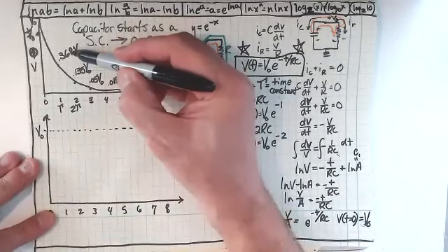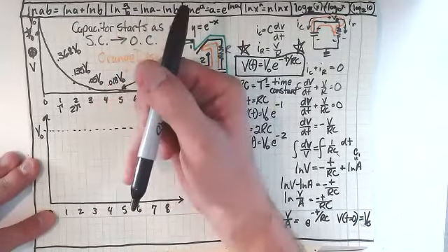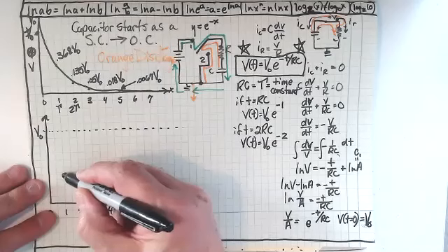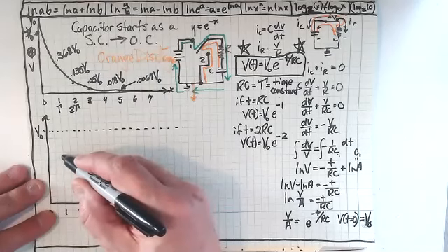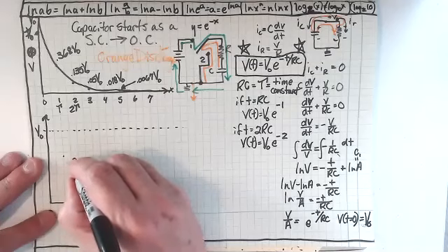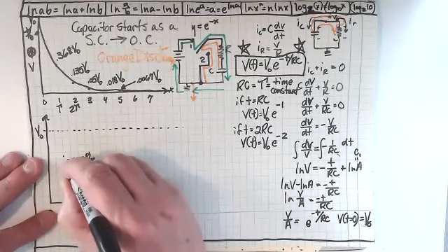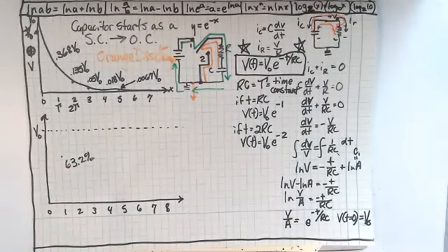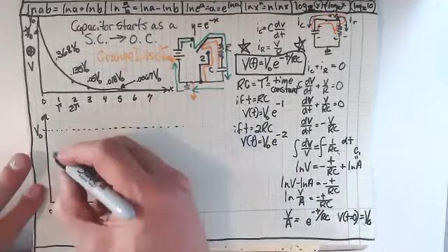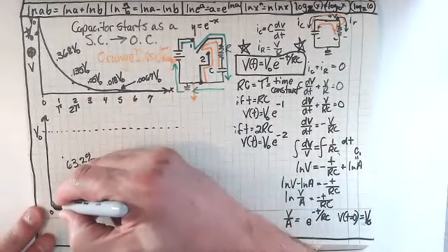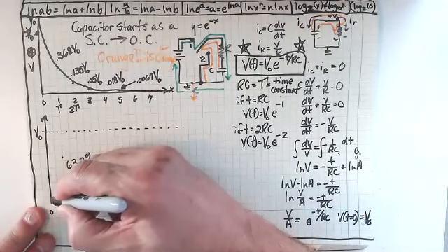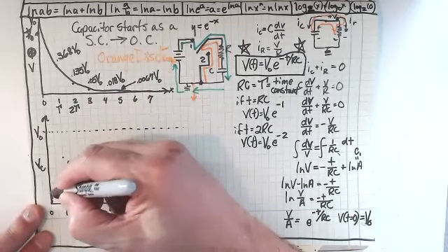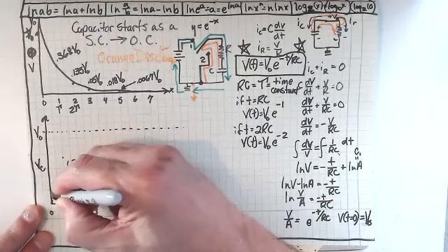So what I would do is take the 36.8% off 100%, and that would give me 63.2%. So 1, 2, 3, 4, 5, 63.2%. Let me just write that there, 63.2%. We'll work with percents now. I need more room for percentages, and I need another one of these pens. Oh, this one looks good. All right, so when I'm just charging a capacitor, there's going to be the voltage across the capacitor that starts at 0, right? And then starts to increase.